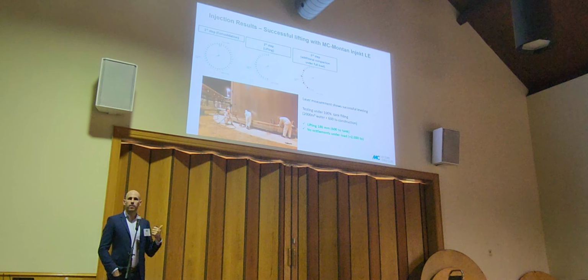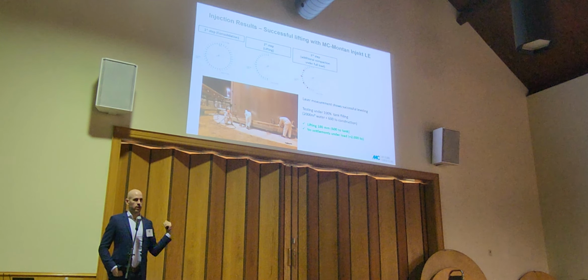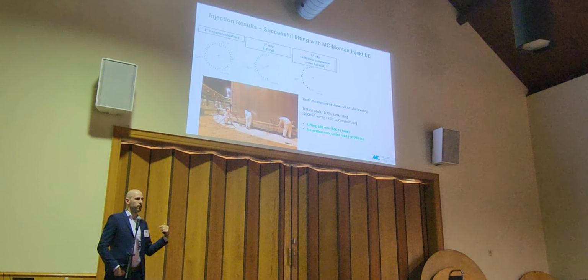First of all, very important, we did again a cone penetration test. The question from the customer, from the owner, was, okay, but you injected a lot of resin, I will just hammer on the resin and I will not see any result. And we explained to him, okay, you will see once you hit a resin lamella, but once you are through, you will see the soil below is also much, much higher consolidated than before.